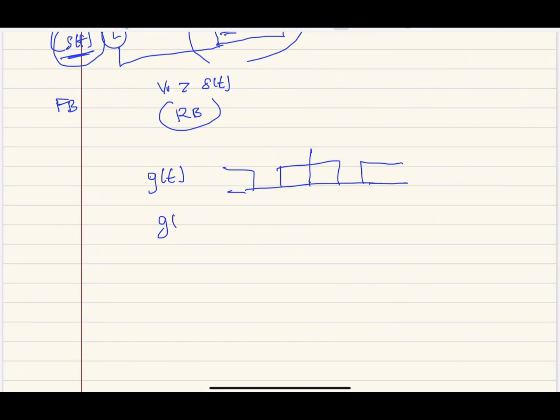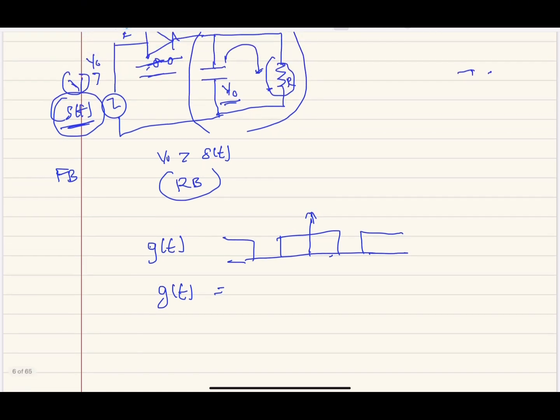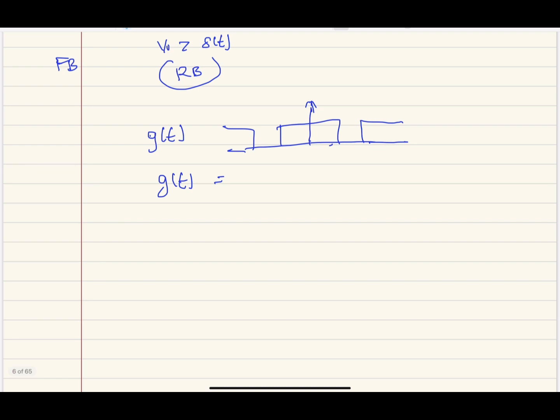Therefore, the Fourier series for the train of pulse: this square wave train of pulse is more like a duty cycle, as I said earlier on. It's being used to control the switching time, the switching of the diode. Therefore, my g(t) is equal to 1/2 plus 2/π cos ωct. I've already explained this, and if you want the full proof of how this came in by using the Fourier series, you can refer to your signals and systems class.